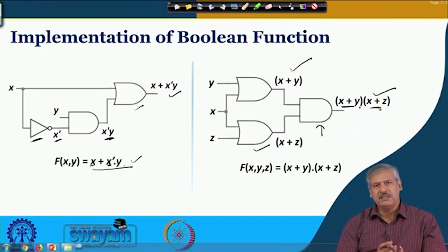Okay. So, we can simply follow any given Boolean expression operation by operation with the operands that are there. If there are 2 operands, 2 input gates will be required, if 3 operands, 3 input gates will be required, and finally, the whole expression can be arrived at in the form of a digital circuit implementation. Remember, in this case we are not talking about the propagation delay, power consumption and all those things, it is just a simple implementation of the Boolean expression.